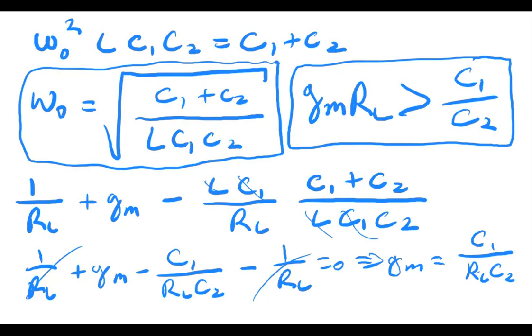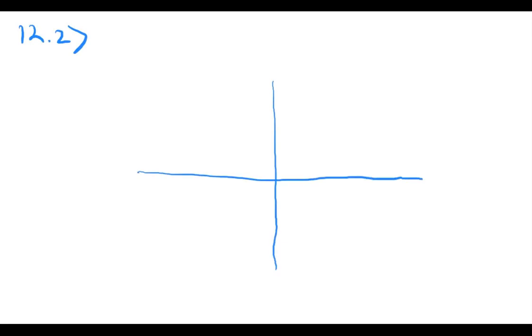power amplifiers is when you're driving a lot of current, you start dropping voltage at your output. That is, you have a voltage gain of 1, and you start dropping some of that voltage on the transistor itself because the current is so large. So ideally, this is problem 12.2. Ideally, in a power amplifier, you want the output voltage to be the same as your input, for the sake of efficiency.